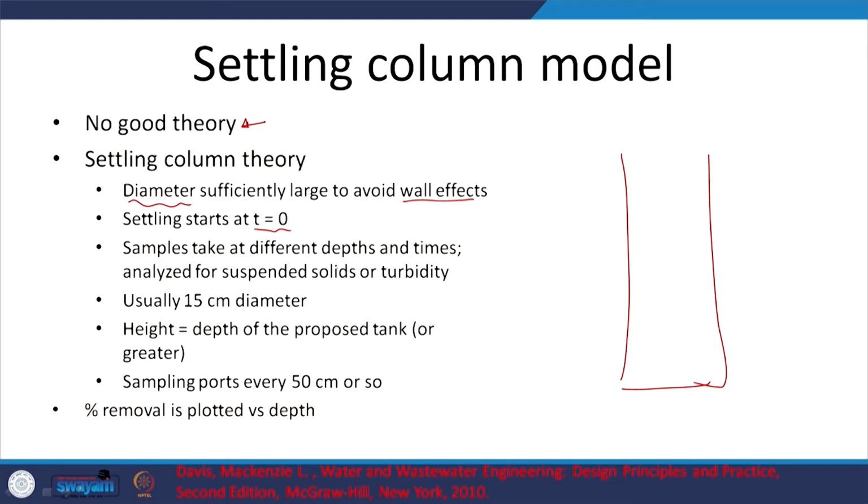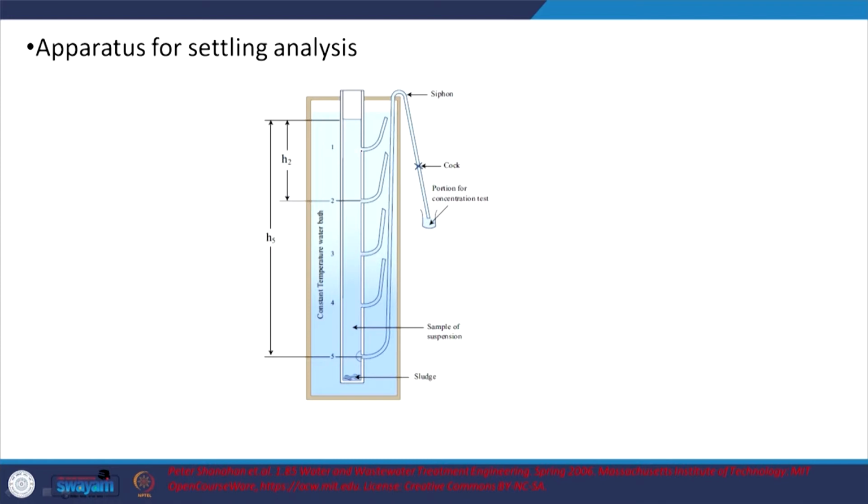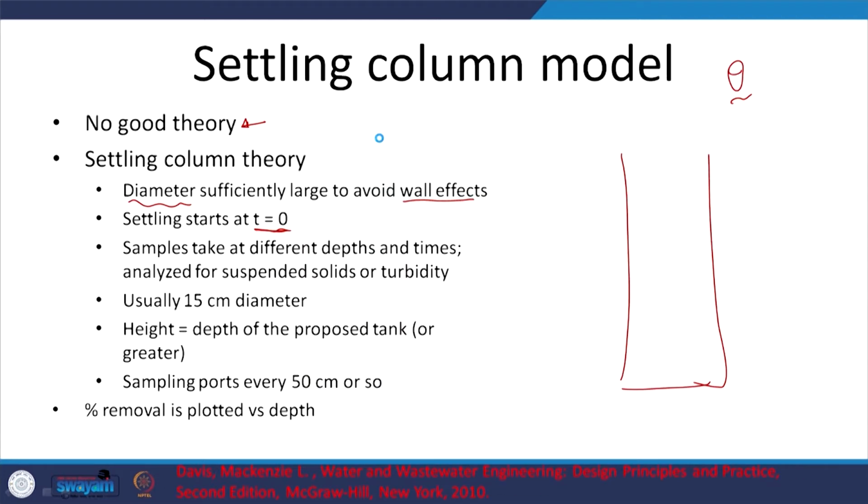When I say time equal to 0, how do I interpret that, or what information is that giving me in a continuous flow system? In a continuous flow system, this time in a batch reactor will be similar to theta, the hydraulic retention time, right? So samples are taken at different depths and at different times, the same depth at time 0, time 5 minutes, 10 minutes and so on. We will look at that.